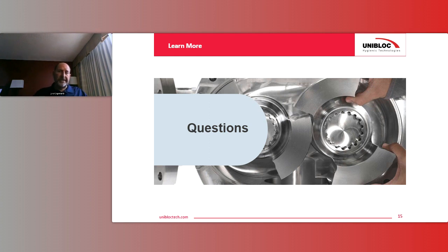Another pump technology for that is called a drum pump, or some people call them stick pumps. Again, you could pull from the top, you put this pump down into the top of the IBC, and then there's two technologies for that, a centrifugal or a progressive cavity. In that case of viscosity, you would need a progressive cavity style. It will pull the product into the pump and pump it out as well.